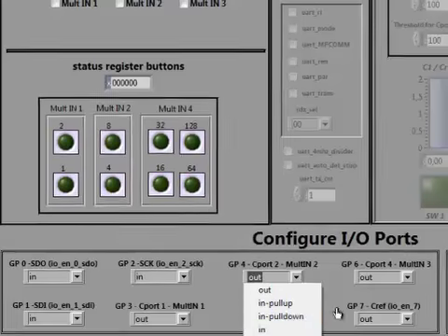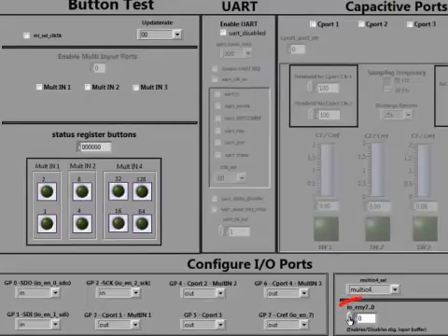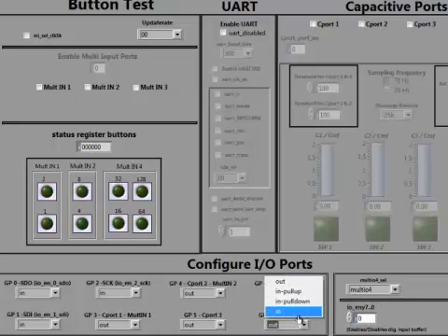When a pin is configured as input, additionally, the respective digital input buffer has to be enabled. These pertain to the settings of bits 23 to 16 in configuration register 11. For example, if GPIO 7 is configured as input, additionally, the 7th bit corresponding to GPIO 7 has to be set to 1.